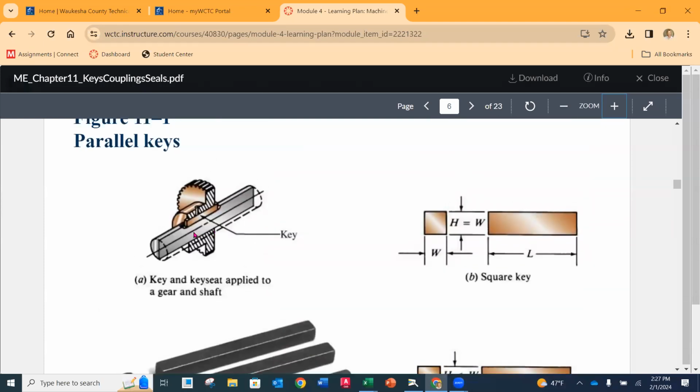Same thing for a gear. If you're not a gear manufacturer, you're going to have to actually order another gear, have it on hand, put that keyway in there, and get it into place. So just as Jesse said, it's there to prevent damage to more expensive, harder to change out elements. Okay, so a key, as simple as it is, is really important to the design, especially when we've got gears, V-belts, and sheaves, the elements we've been talking about recently in this class. And shafts are going to be coming up very soon for us.